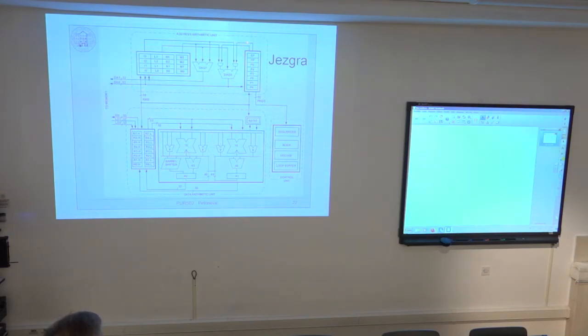But as is shown here, they are used only with data address generator 0. They cannot be used as an argument for DAG1, only for DAG0. So this data address 0 can be generated either based on this set of address registers or with this DSP-based set of address registers. Okay? For DA1, it can be only this one. Okay? Only DSP. DAG1, DA1, only DSP registers.